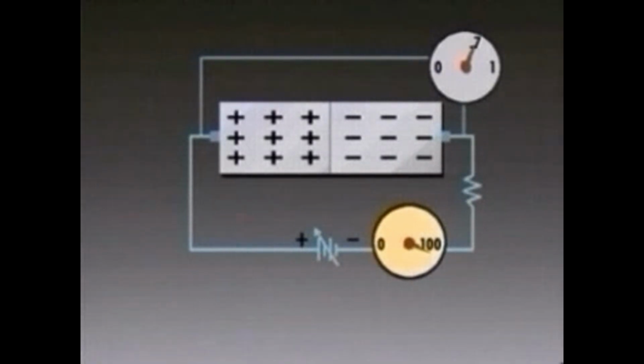As current increases, there is no further increase in voltage across the diode. Maximum forward current occurs when all forward biased carriers are utilized. Any further increase in voltage at this point will increase the voltage drop across the junction. This is called saturation. Operation above this maximum forward current for a period of time exceeding specifications will generate enough heat to permanently damage the diode.